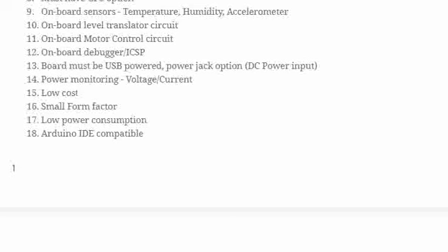And then the product requirements document from the marketing team is also going to mention that the board must be RoHS compliant. That's it. It doesn't have any CE, FCC, or any other requirement. And then verification. Verification wise, what they're asking is your board must have touch points to access, and it must have 50% touch coverage. That's it.